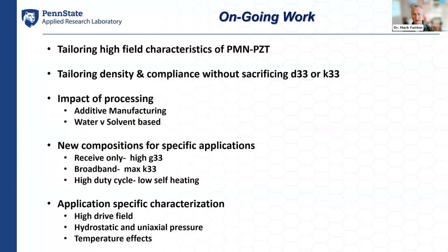One of the things that we're just beginning to look at in the area of energy harvesting is the impact of grain size on the performance of textured PMN-PZT. As you noted in some of the initial diagrams of microstructures, the grain size of the textured material can be 4 to 5 times, if not more, the grain size of a traditional PZT material. And there are a lot of open questions regarding the impact of that grain size on, say, fracture strength of the material or the impact of cyclic fatigue as a function of grain size as well. And we're actively pursuing those questions as well.